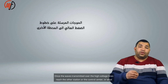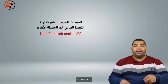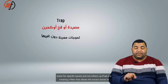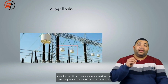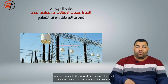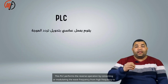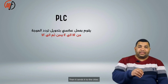Once the waves transmitted over the high voltage lines reach the other station or the control center, they are captured by what is called a line trap. The term trap here means a filter or a snare for specific waves and not others, as if we are creating a filter that allows us to capture communication waves from the power lines and then pass them to the control center where they are received by the PLC device. This PLC performs the reverse operation by converting or demodulating the wave frequency from high frequency to intermediate frequency. And then it sends it on.